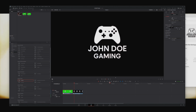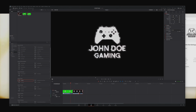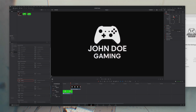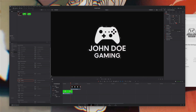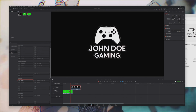If you play the video, you can see our logo is a bit bigger than the animation, so let's fix that right now. Drag the logo up to the video track 2 and move it so that it overlaps with our animation. Now in the inspector, let's change the zoom down so it matches the animation size. It looks like my magic number is 0.95. Now we can move our logo back to where it was.